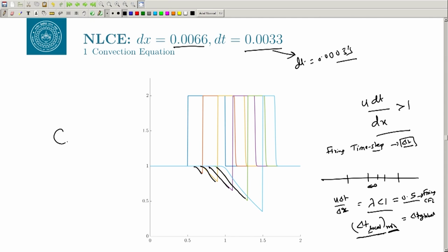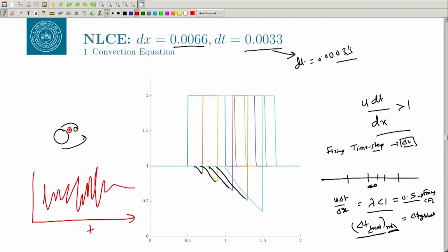So, there is a flow past a cylinder, and you are having the vortex shedding, and you want to find out at what frequencies the vortices are generated, right. So, what will you do? You will put a probe here, for example, at this x point, and you will measure your signal, that is what you are measuring. So, this is your time, and let us say your velocity.